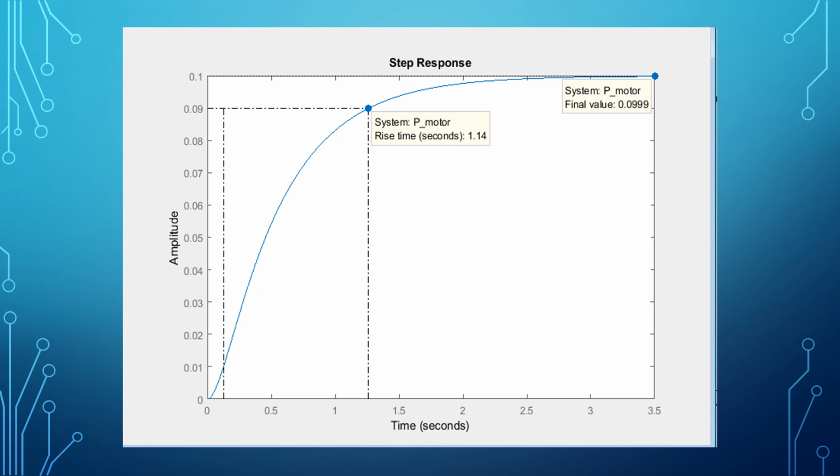The first graph which I've added here is the open loop response. And you can see as the final value I'm shooting for a 1, and it is not a 1. So in order to reach this requirement, I'm going to have to add the integrator value.